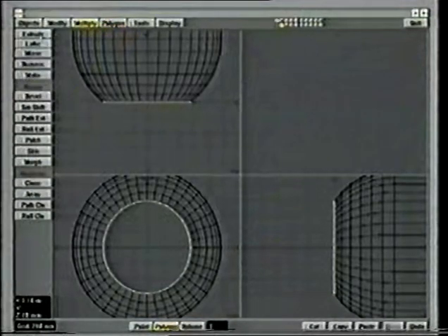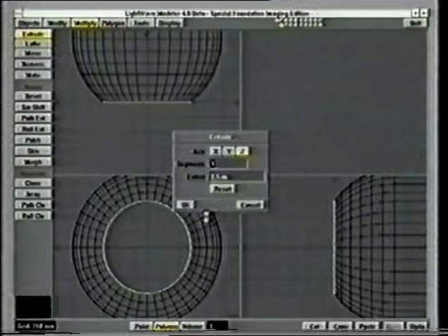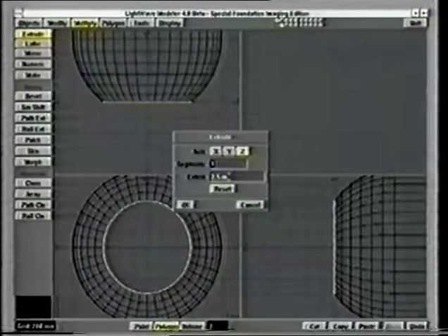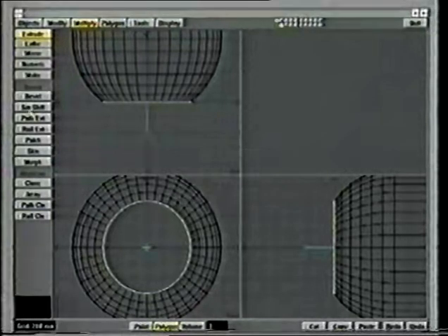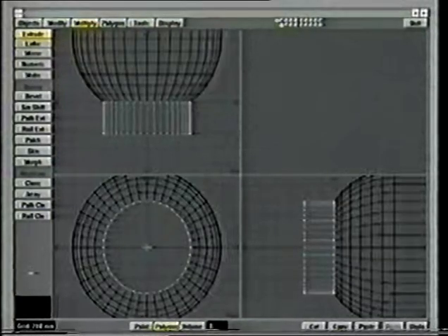So I'll flip that polygon with the F key, multiply, extrude, numeric. So I want one segment. This one, I've got 200mm. I only really want to go, say, 400mm. So I go 400mm minus, enter, and make it.